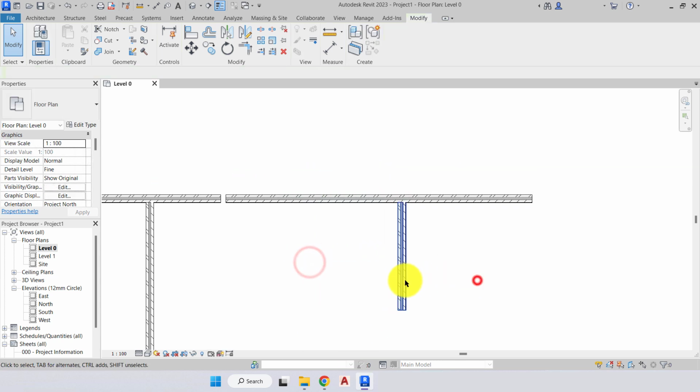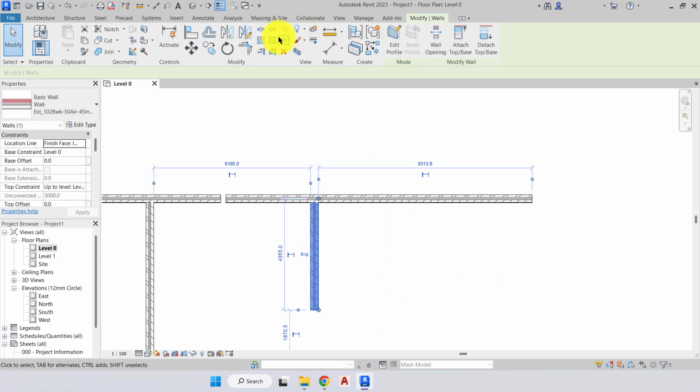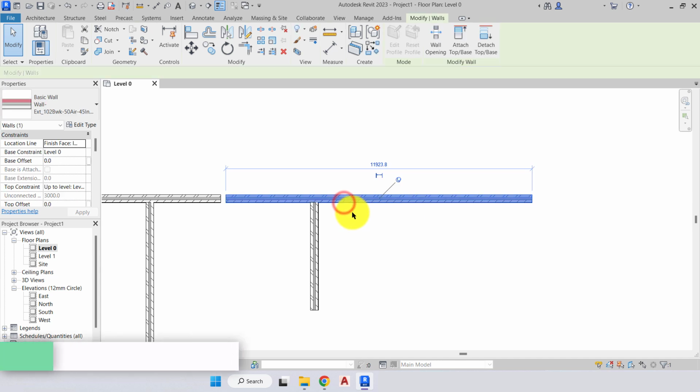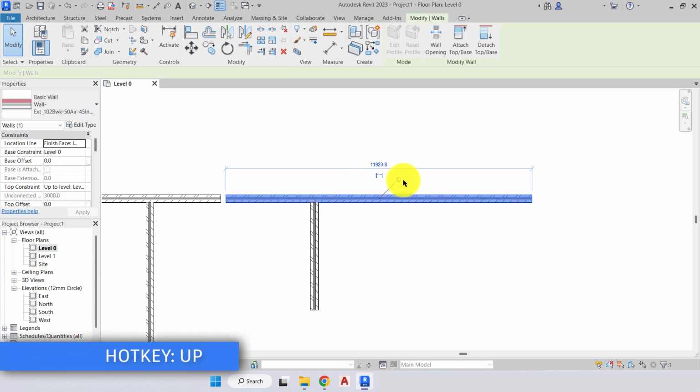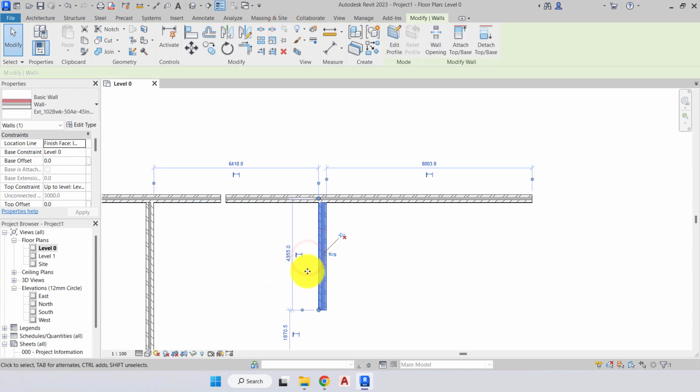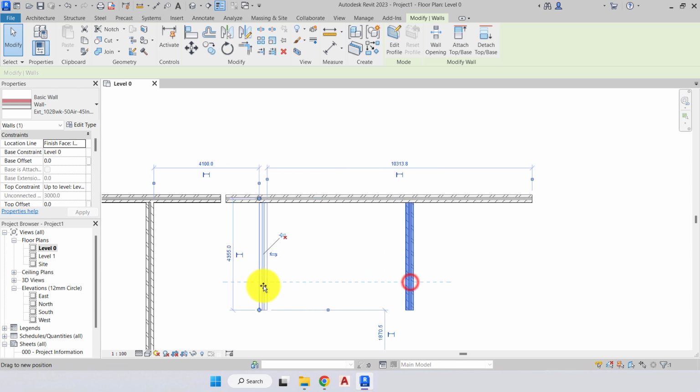Anything that's attached to it can still be moved until we place a pin on that too. So when we create our project, it's essential that we pin down our walls, doors, and windows so they're not easily moved without us knowing and disrupting our layouts. To unpin those components, we just simply select it, and we can either choose the pin option here or come back to the panel. And now the walls are free to move within the project.